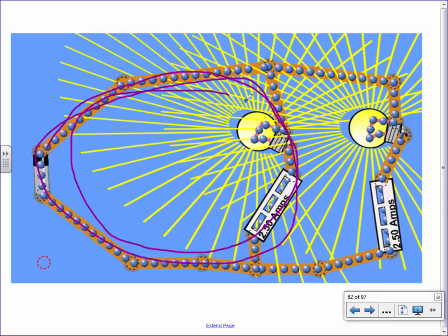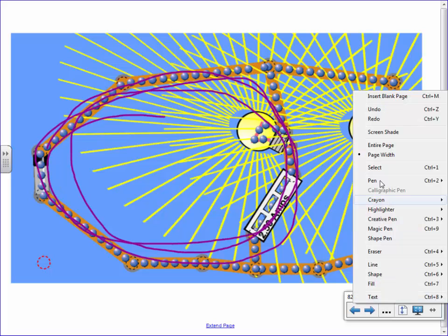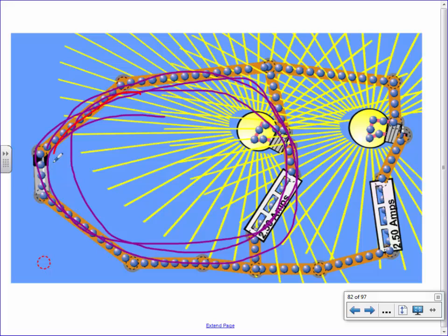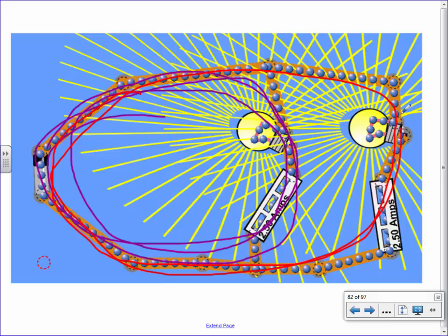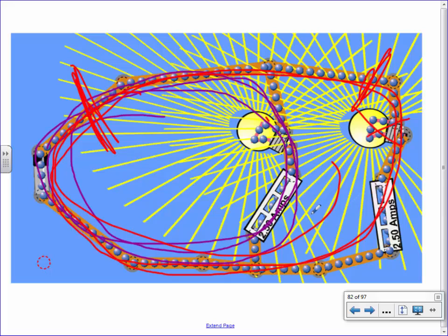So this light bulb gets its own loop, whereas the other light bulb also has its own loop. Now I know some of the wires are still shared, but it has its own independent path. If this light bulb right here were to break, the purple loop would still run. Does that make sense? Because of that, each of them actually has full amperage because they each have their own path. Now, if this wire right here were to get cut, the whole thing would be broken, obviously. But if this wire were to get cut, at least the other one would still work.